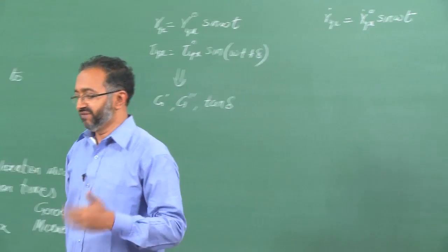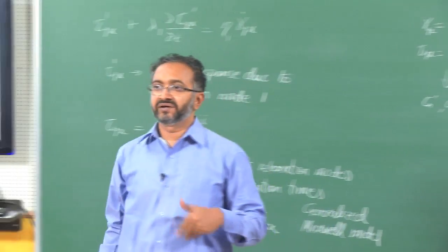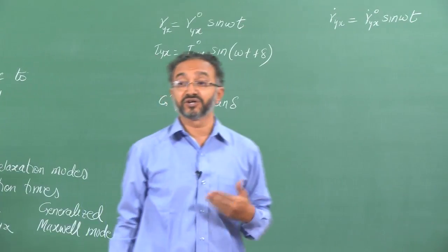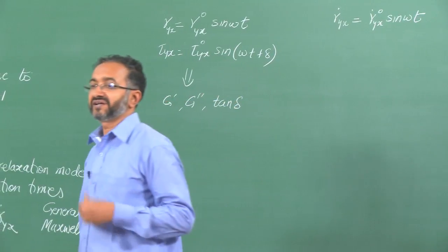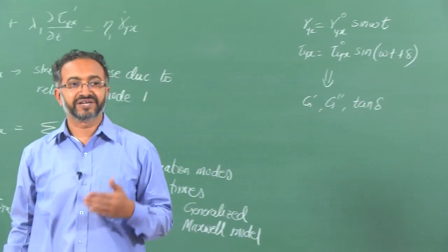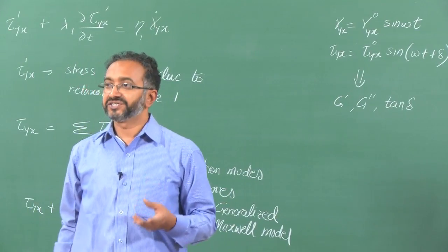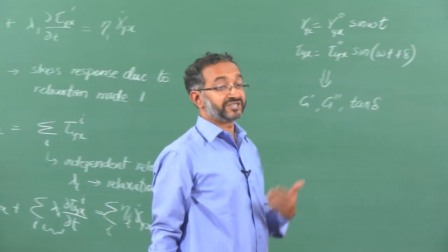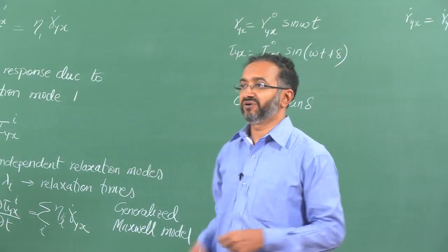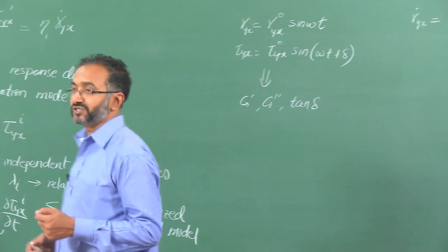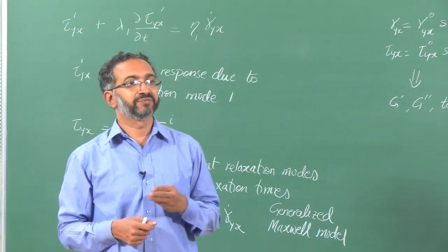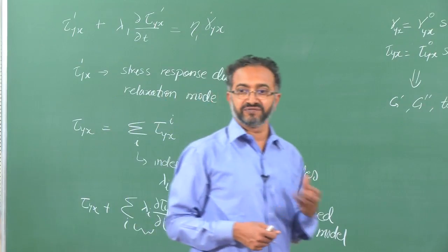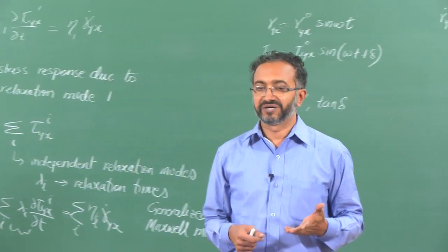So, this is something which in rheometers and their construction, there are different controls possible. So, we can either control the torque or the stress, we can either control the amount of rotation or strain, or we can control the rotation rate or strain rate depending on what is available. And of course, a lot of this is also done with feedback loops and control loops and the usual instrumentation procedures which we use for any instrument.